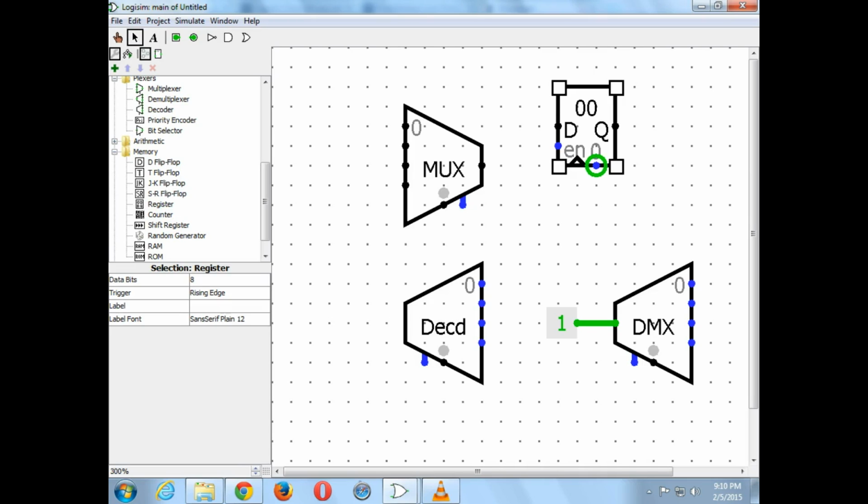Why have that instead of just data that's all zeros go into it to reset it? Because you cannot specify. This is a global thing. The reset pin is one single wire that is connected to all parts or all important parts of a processor. So when this pin, the reset pin, is asserted, meaning it is a 1 in this case, then all components will simultaneously reset to a default state. And without any special specification, the reset condition is always 0. So this register will reset to 0 when that pin is a 1.